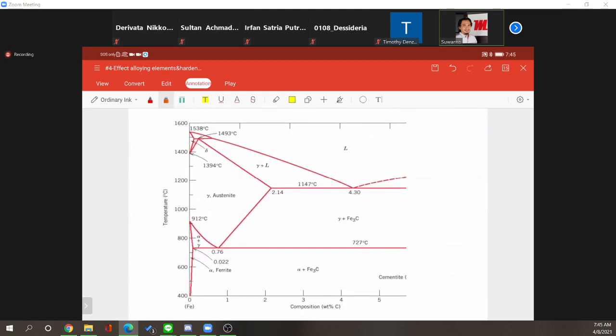Well, later on we can also discuss this slide. Maybe the arrangement of the slide is not perfect yet, but you see that this is for a normal phase diagram without any chromium. So there's no chromium, no nickel, no manganese. This is just iron with carbon, and the carbon content is different, which is actually written here.